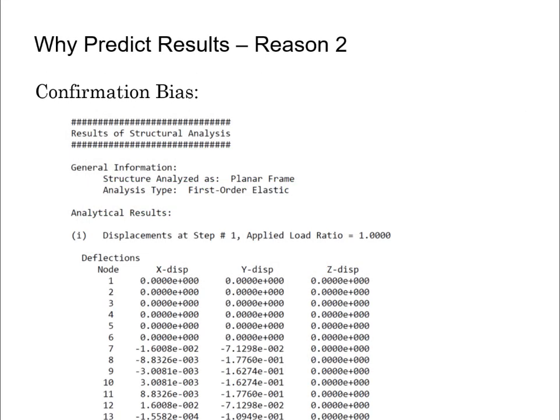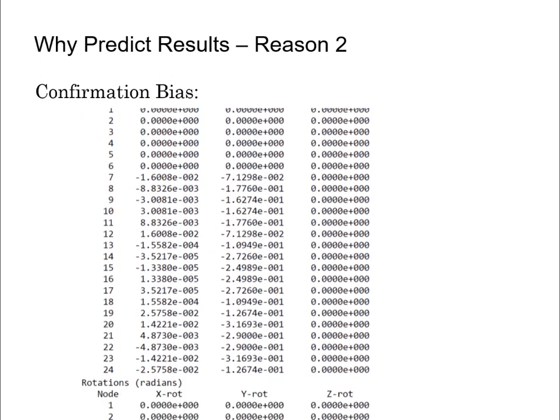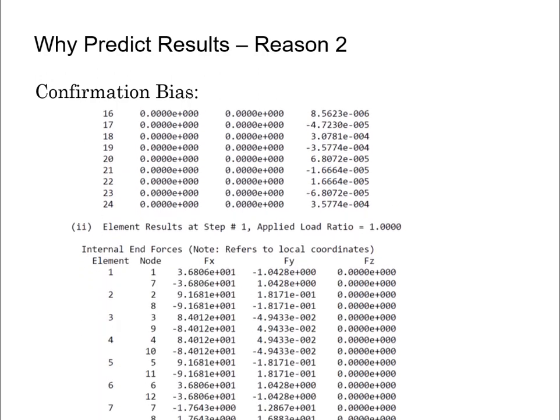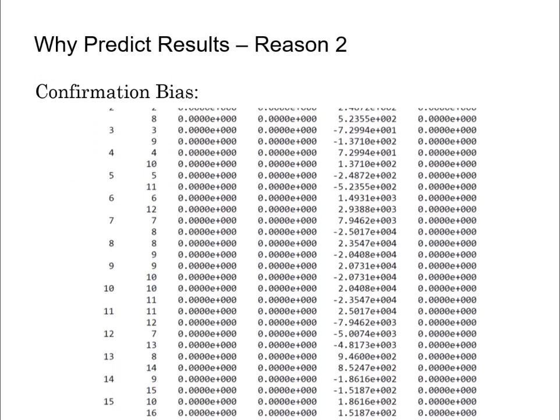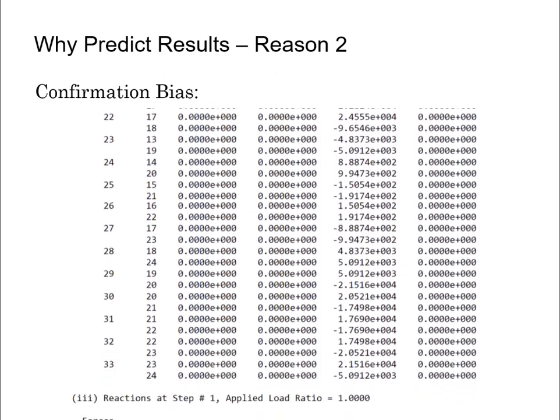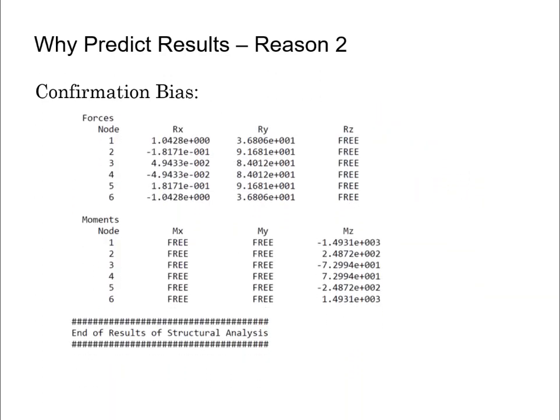Computer-aided analysis creates a huge amount of results, even for a very simple structure. There are internal forces and deformations at each end of every piece of the structure. If we are working with a three-dimensional model, that is 12 pieces of information at each end of each piece. Do you see how we can reach data overload?